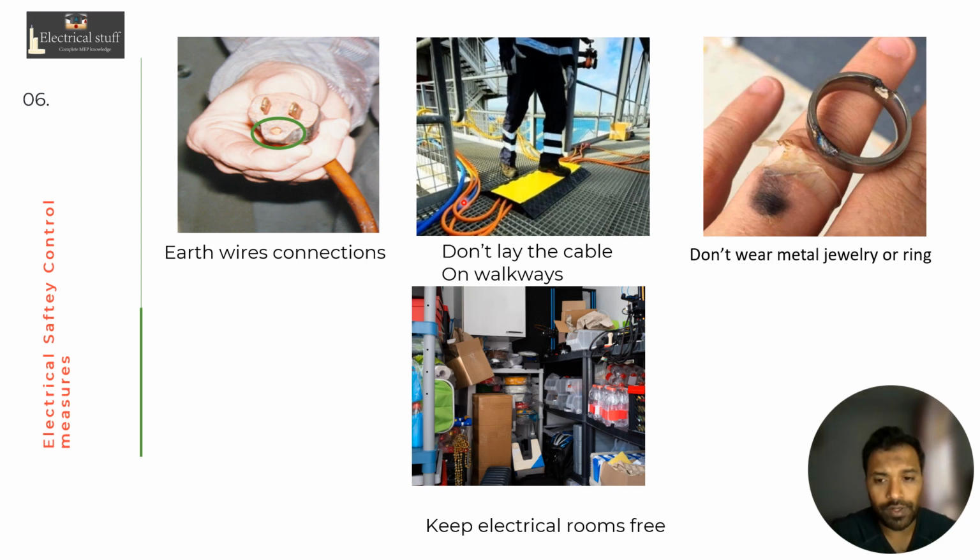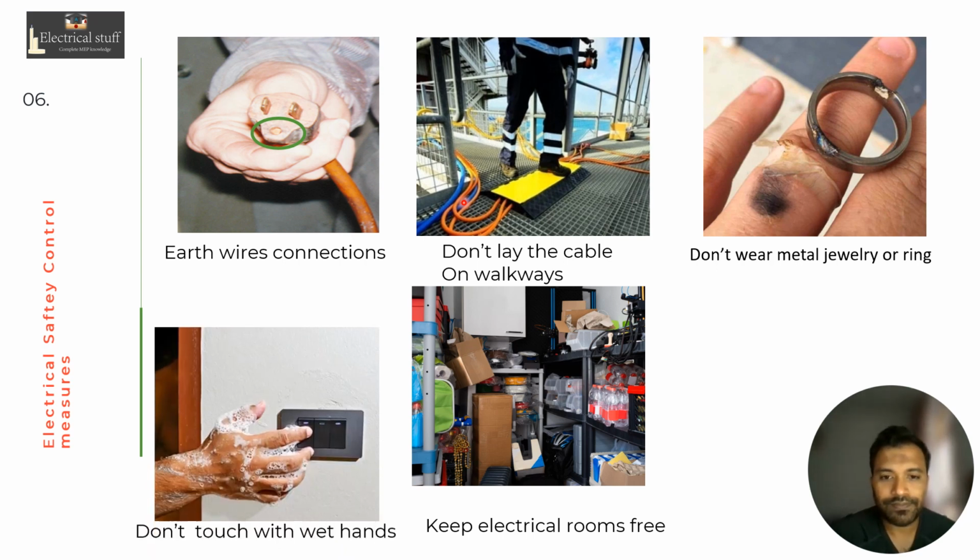Keep electrical rooms free. I see many electrical rooms where people think it is a dump yard, and they put ladders, tools, and many things. Don't put them. If there is any chance of arc flash, it will ignite the entire room, the entire room will catch fire, and this fire will spread through the whole building.